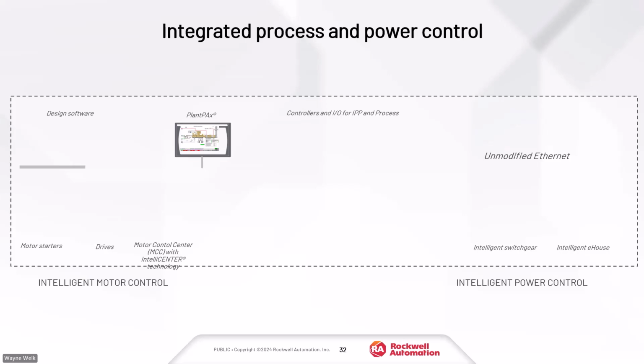Several years ago, there was a standard network protocol called IEC 61850, and that technology is able to capture those trips from the switchgear at millisecond resolution and communicate that out over a network to an automation system or to an HMI system or a SCADA system. And so that's really the increase in technology that's happened recently to make intelligent switchgear and intelligent e-houses a lot more capable and more cost effective to put in. So you can go ahead and go to the next slide.